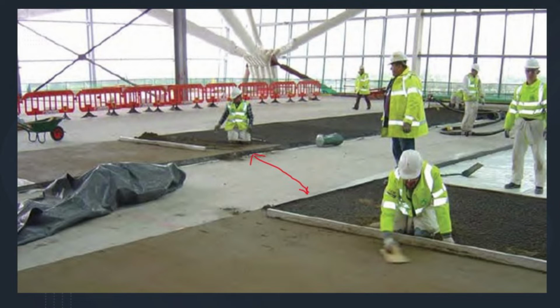One day, whenever you take the full width of a hall, you have to divide it into 3 meters, and always take alternate panels in a day. The panel can be made using a C channel or a pipe or a ply, whichever is suitable. It should be made with 3 meters. So today you are casting panel numbers 1, 3, 5, 7. Tomorrow you can cast 2, 4, 6, 8.